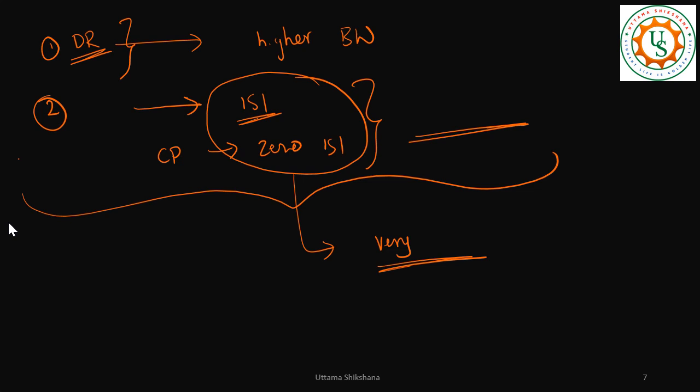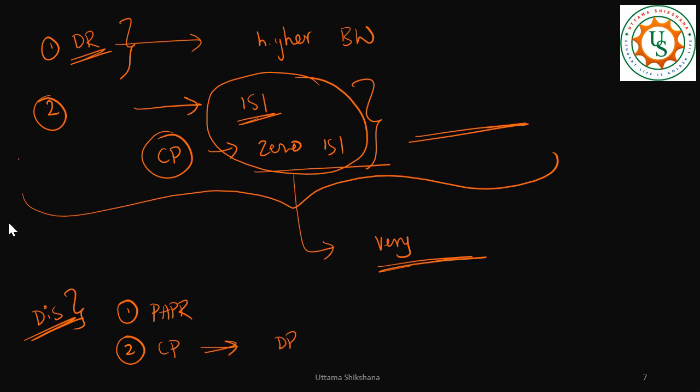But of course, there will be questions like disadvantages as well. With the concept of OFDM, there were many disadvantages, like high PAPR issues, and of course, we had many overheads. Like even in case of CP, right? To eliminate this ISI, we added CP, but it has decreased the data rate a little bit. But this overhead is okay for us. And even increasing the bandwidth has brought challenges in developing some of the filters, wideband filters, right? And even we had challenges in developing the filters which have very little roll off. We had challenges there as well.